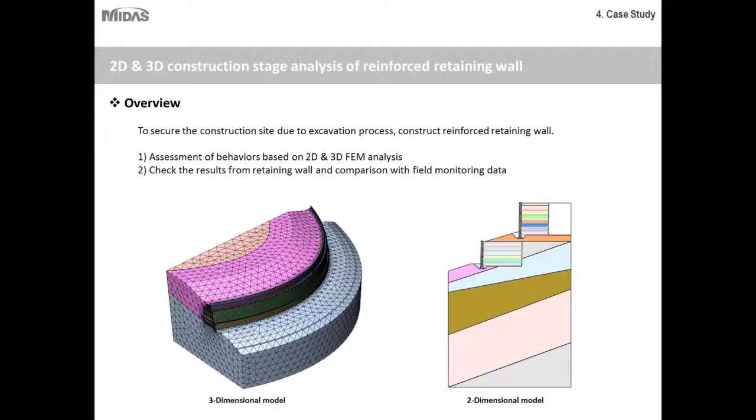So why did they need 3D and 2D analysis models? As I mentioned in the very beginning, sometimes your reinforcement layout varies along the length, or your section varies along the length, and then you need to move one step ahead of 2D analysis, which is 3D analysis. And as you can see, this is not a regular structure, it is changing, it's a continuous structure.